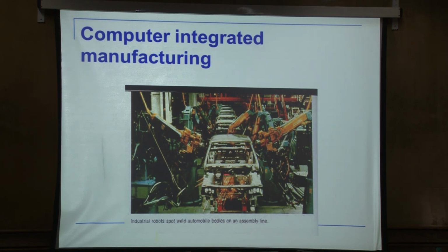how this programming is actually done in the industry is that they would have a CAD model of this. So they would initially have a CAD model of the car, a CAD model of the robots, and the full cycle time will be optimized on the CAD model first. So in simulation, they'll be optimizing the cycle times: which weld is to be done where, what is the cycle of the weld, what's the direction of the weld.